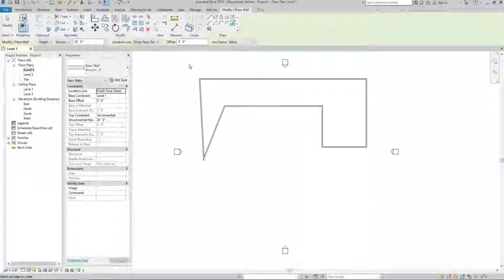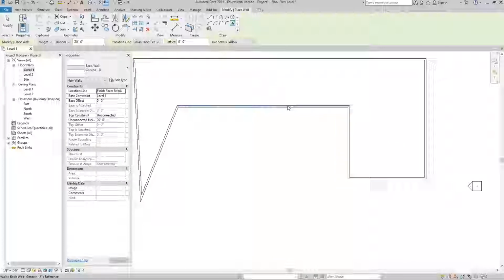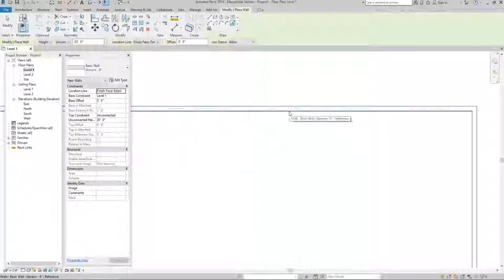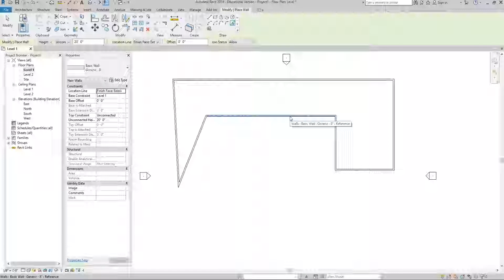So I clicked on pick, and I come down here, and we're not really sure quite what to do yet, right? Number one, down here in our kind of shortened command line, if you ever get lost in a command and you don't know what to do next, this says select an edge or line. Okay, so number one, we know we have to select something in order for this command to work, right? So that's true, all right? I have to select something in order for this to work, but there's another definition I have to use before I create my selection, and that is I have to specify an offset, all right? And the offset is how far I want my second object to be formed from my first object.